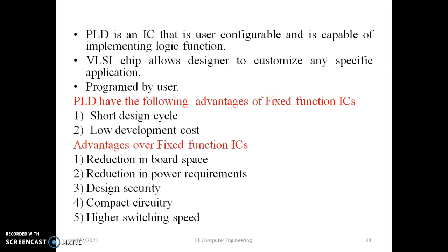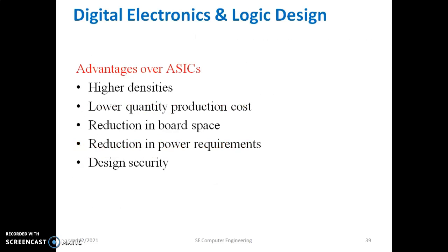First one is the reduction in the board space, the reduction in the power requirement, design security, compact circuitry or higher switching speed. With regular ICs the complexity increases, so that can be easily reduced with the help of these PLDs.